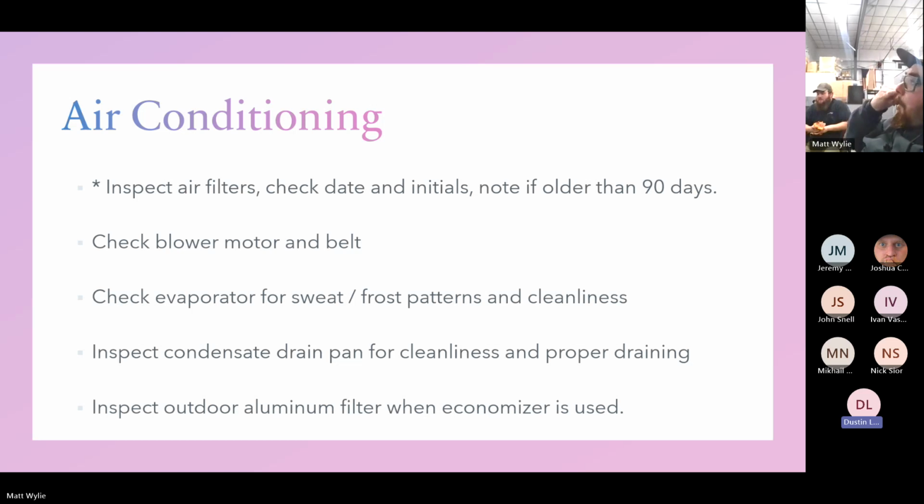Like now you're not building up enough heat to get a proper supply air to heat the building. And so, yeah, it's great. Your motor works and your belt looks good, but is it the right belt? Is your motor pulling the right amps? I always look to see what the amp rating for the motor is, and then check my own amp draw. A lot of these units too have an adjustable pulley.